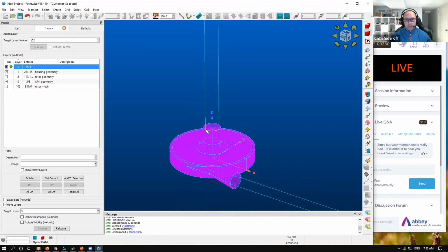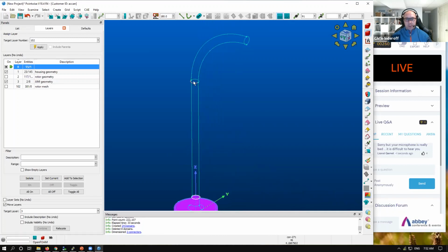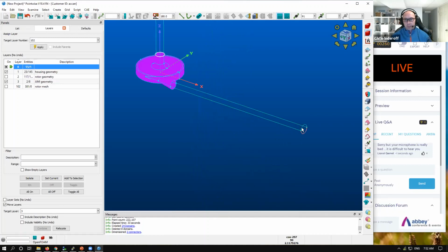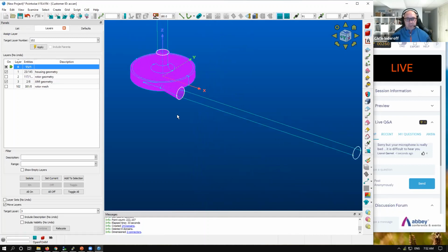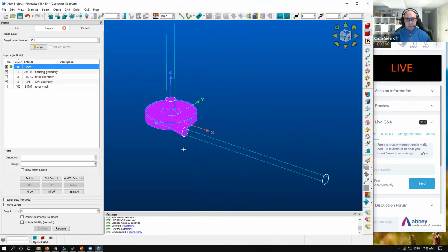We also have these semicircular connectors here. I'm going to make them all a nice round value, so change them all to 51. Why do I choose 51? Because it's the number of points. 51 will give me a nice even number of intervals, 50, because intervals are the number of points minus 1. So if I choose 51, I get 50 intervals. So change it to 51.